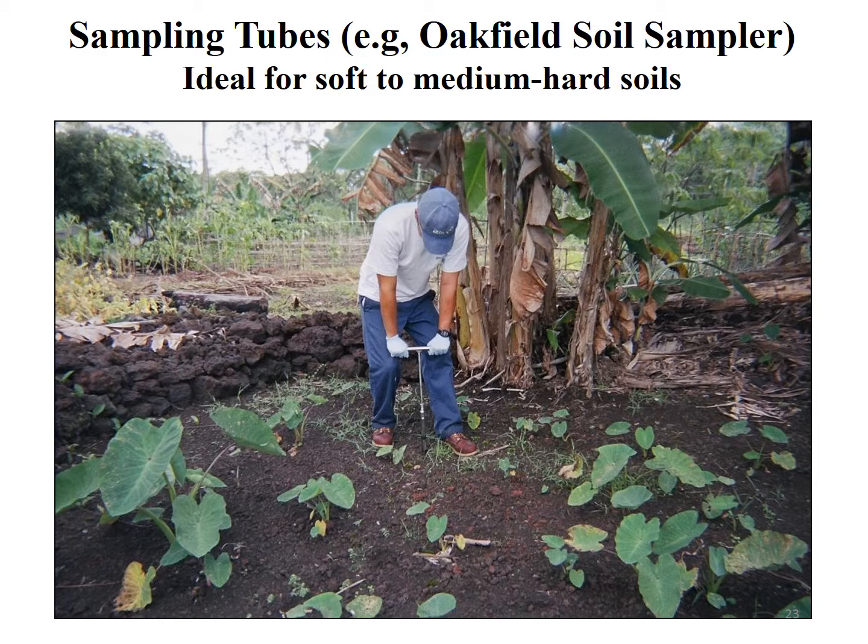In some soft soils, you may even be able to collect as deep as a 0 to 12 inch core and then split that in half to determine if contaminant levels decrease with depth, especially if the analysis shows that the targeted 0 to 6 inch depth shows contamination over applicable action levels. You'll then want to look to see if the lower depths are contaminated above your action level as well.